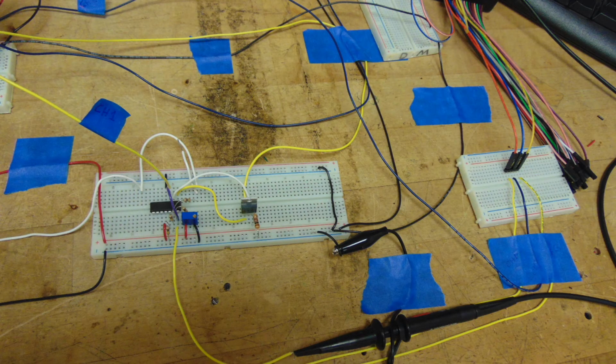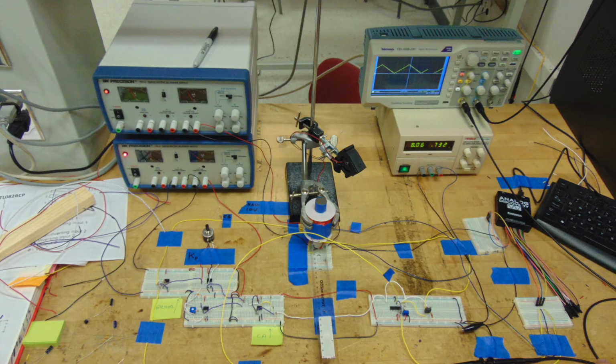The ultimate gain is the proportional gain at the point of oscillation. The ultimate period is the cycle time at the point of oscillation. The values of the ultimate gain and the ultimate period are used with the Ziegler-Nichols equations to determine the PID controller gain, integral time.